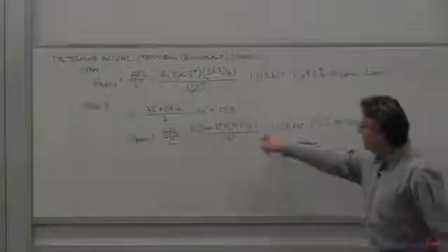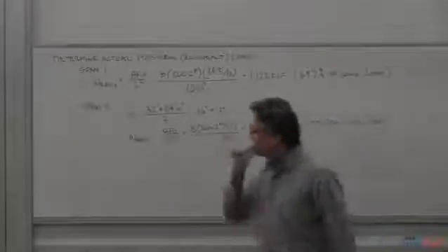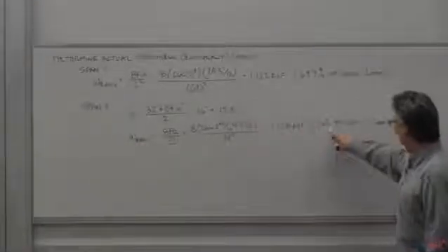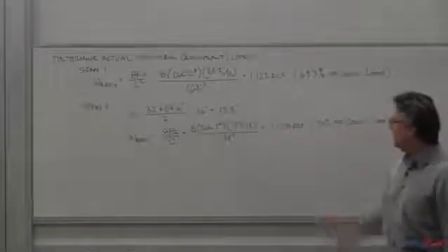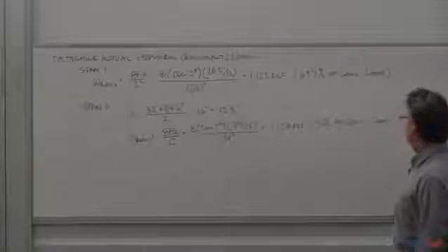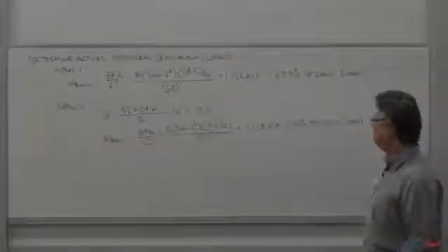Okay. Basically, because this 12.3 turned out to be exactly what I started with, I get exactly 70% of the concrete load in the second span, 1.128 kips per foot.